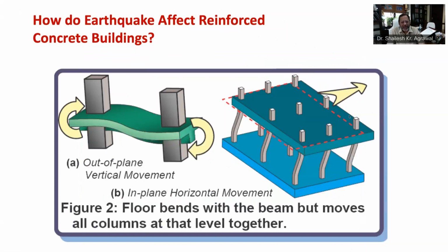Now let's see how floor slabs and masonry walls participate in earthquake-induced shaking. Floor slabs are basically horizontal plate-like elements which facilitate functional use of buildings. Normally, beams and slabs at one story level are cast together. In residential multi-storied buildings, thickness of slab is 4.5 to 6 inches.